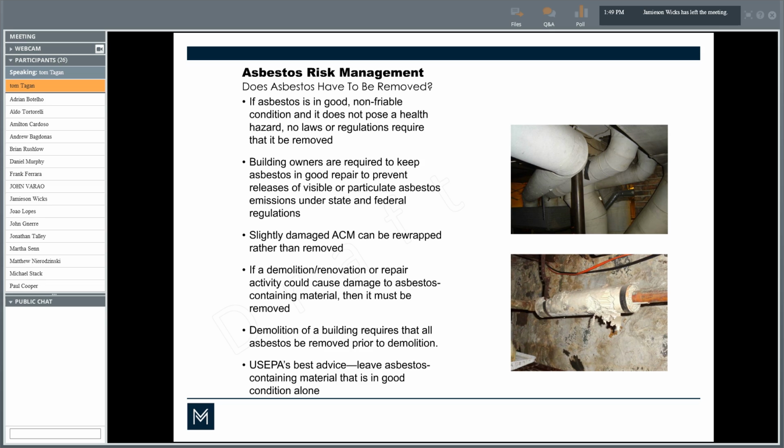Where it becomes difficult is when you get to the mudded connection. That's where you have like an elbow or a T-section in your piping. Those things were never really able to just be fit easily with asbestos materials. And as such, they put asbestos in a cement and essentially just put it around the connection to try to keep the heat inside that piping. As such, those units, you have to almost chip them off to get them out of there, which is a lot different than basically being able to cut a piece of insulation tile or piping and be able to unfold it and get it off the pipe.